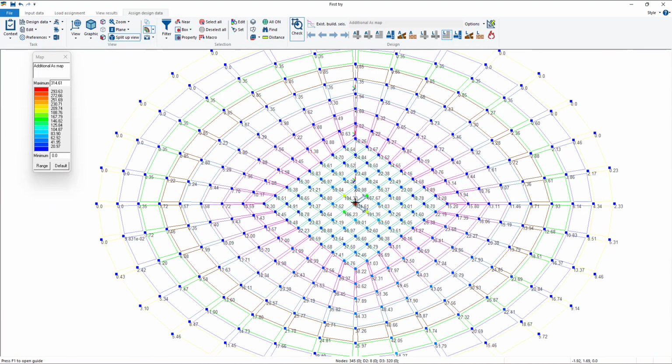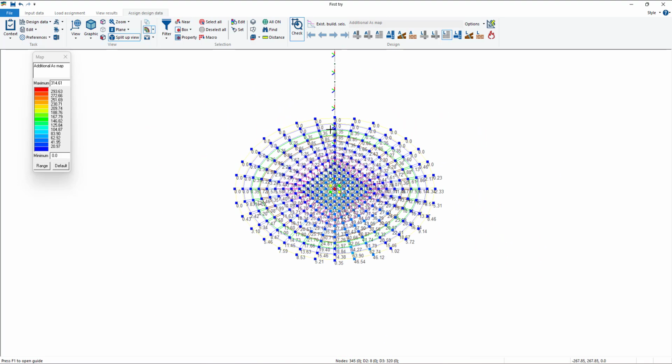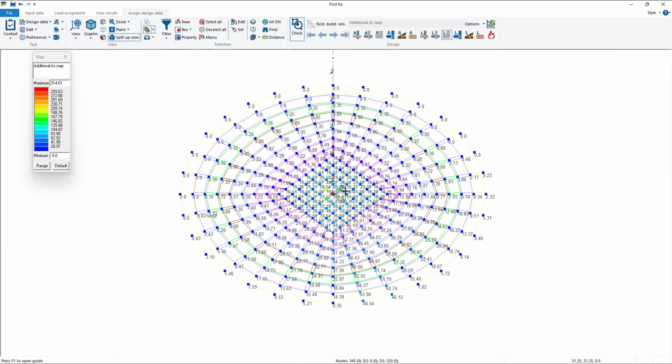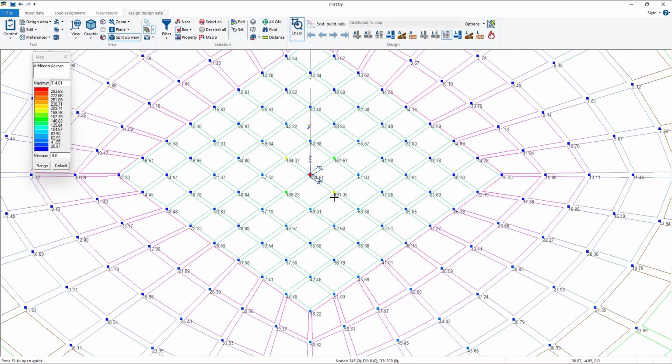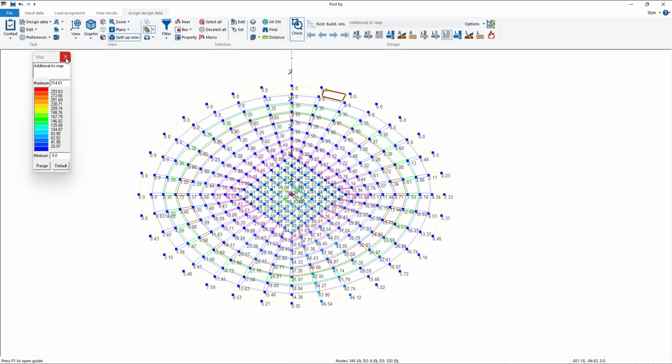So to avoid this problem, we can choose another kind of modelling for this element. And for example, we can use a cylinder of three elements to basically distribute its weight all along a line of nodes and not just a single node. Or another thing we can do is use rigid links to distribute this weight on the near nodes. So first of all, I want to select an even bigger diameter.